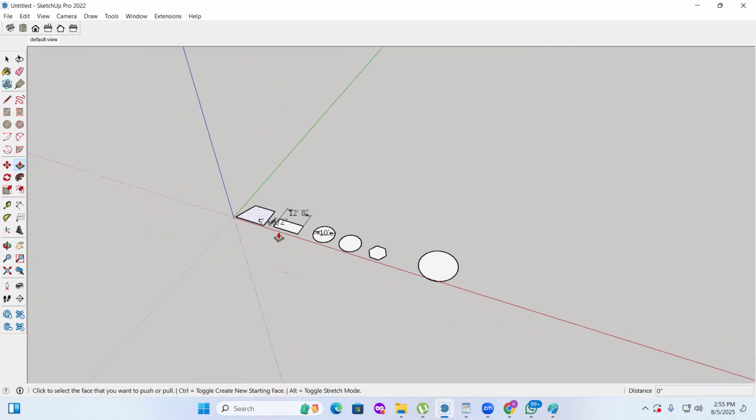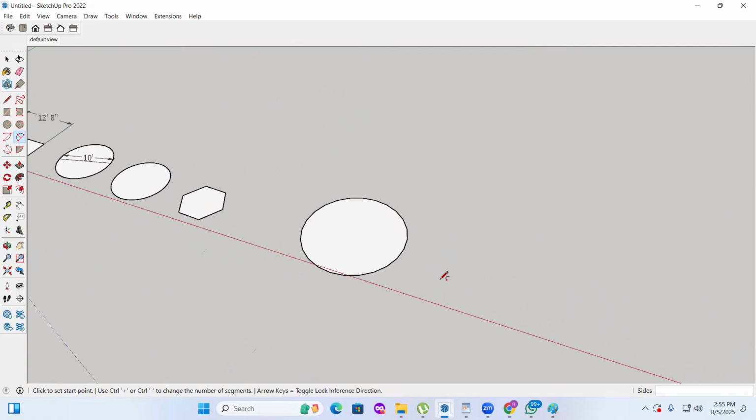And finally, one thing is there. What is that? Arc tool. Click here. What is the tool name? 2-point arc. 2 points. First of all, you need to provide the length between the 2 points. Point number 1 and point number 2. For example, I'm giving like a 20 feet over. And between this, you can enter the line, the curved line.